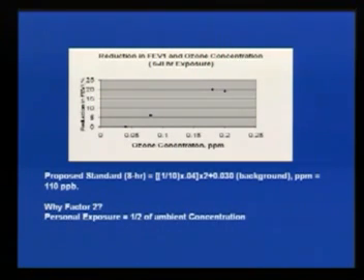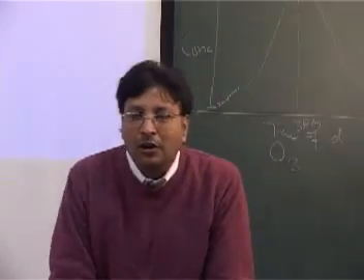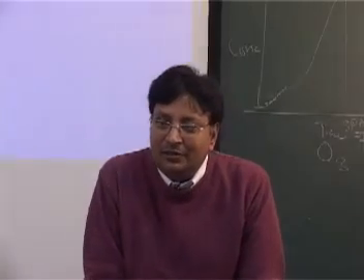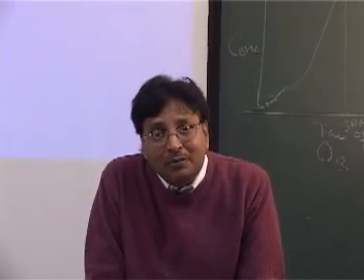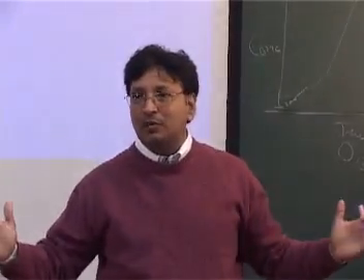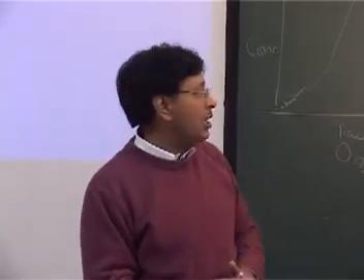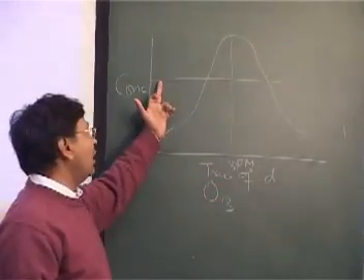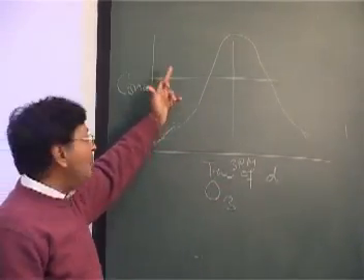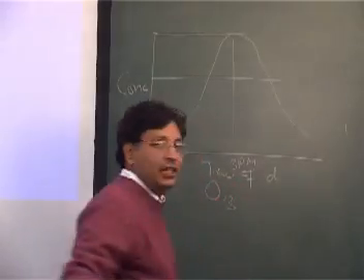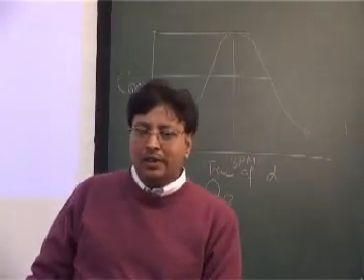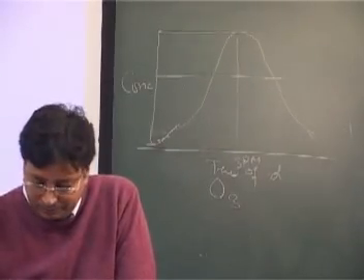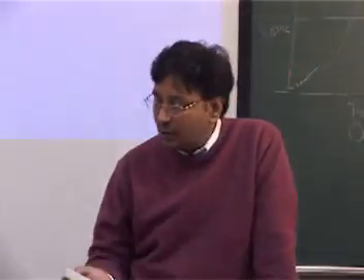Which standard will be lower, the 8 hour standard or the 1 hour standard? The 8 hour standard is lower, because the exposure time is more, so the averaging time is more. Suppose I have to fix the 8 hour standard, then the 8 hour average concentration can be fixed here, but for 1 hour I will fix a different standard. So this is important to understand how we deal with the problem. Very good. Let's go further.